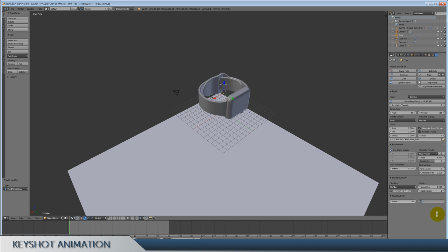The amount should be like 0.1 or something like that, or maybe even 0.01, just for a start, so you see if your PC can handle this simulation and it's not taking too much time. Like I said, I'm going to leave it at 0, but you should add at least a small number, in order to make it look real.